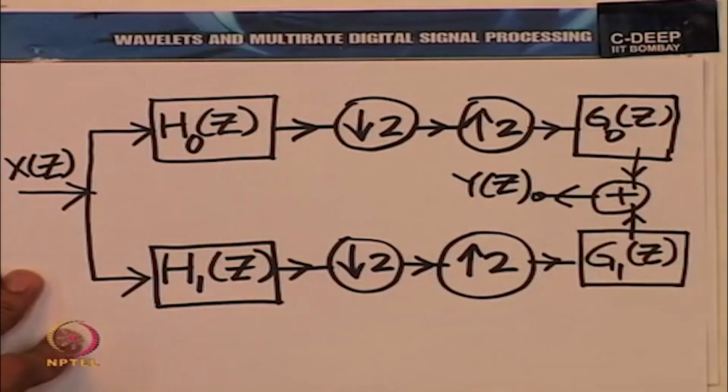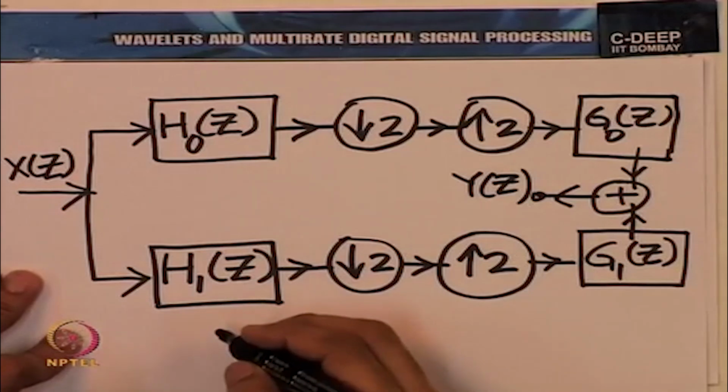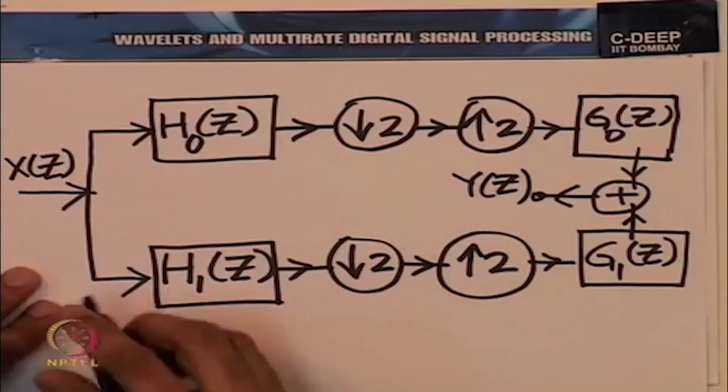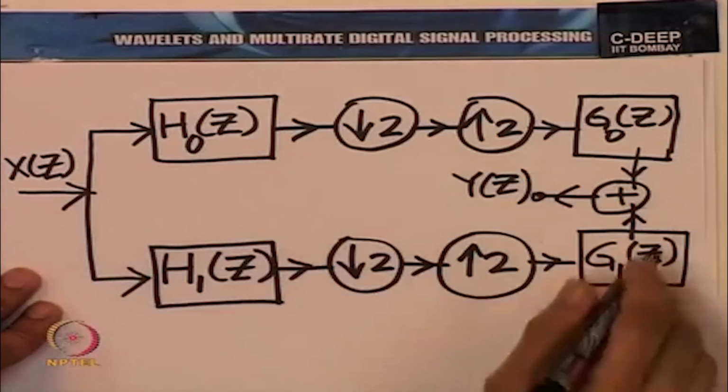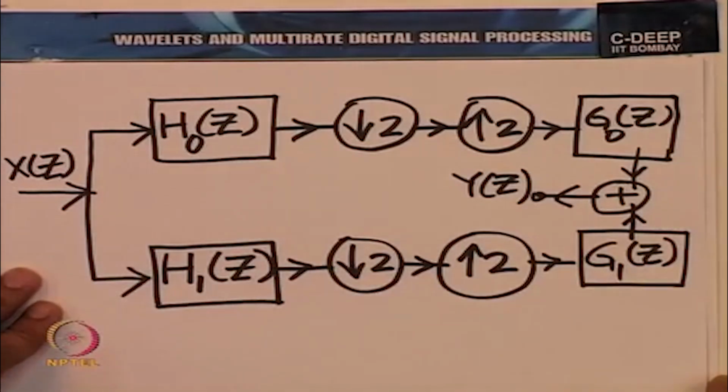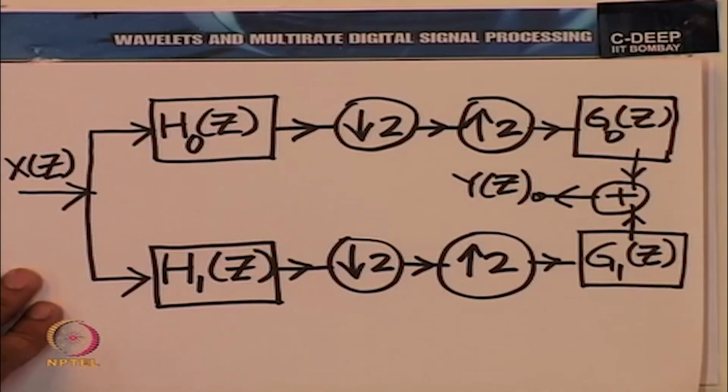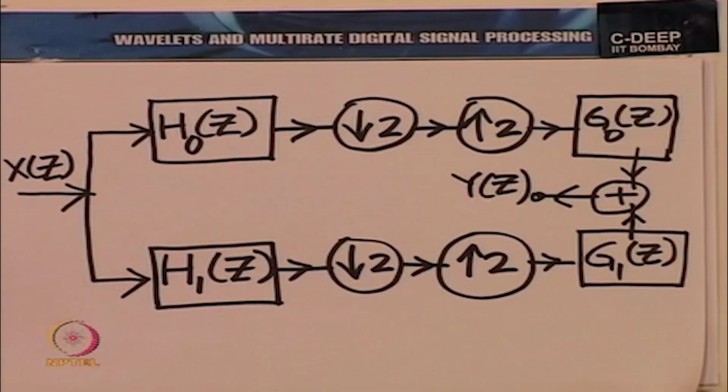And what we intend to do finally today in this structure is to relate the Z transforms at every point in this structure. Let us start doing that, and to do that, let us first recall what happens when we go past a downsampler and an upsampler. So, as I said, let us look at the upsampler first, a recall from the previous lecture.